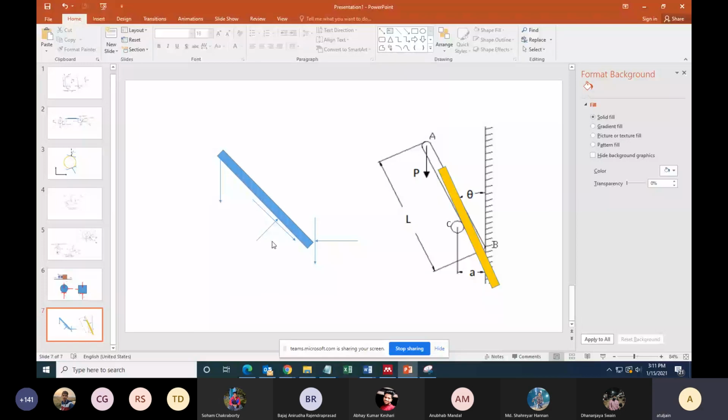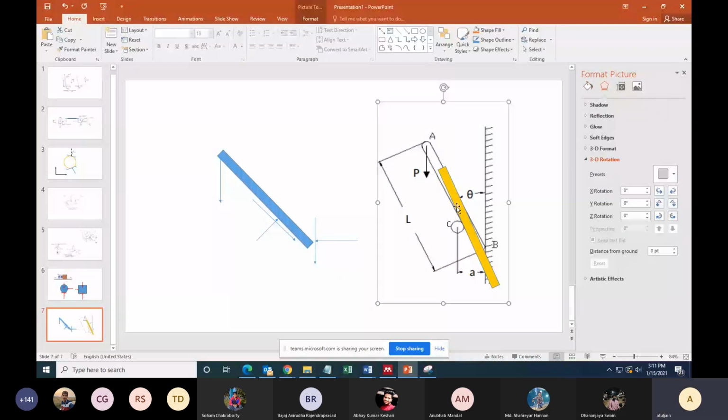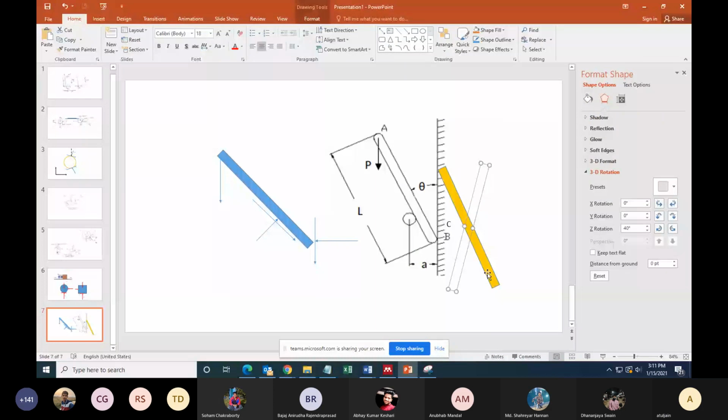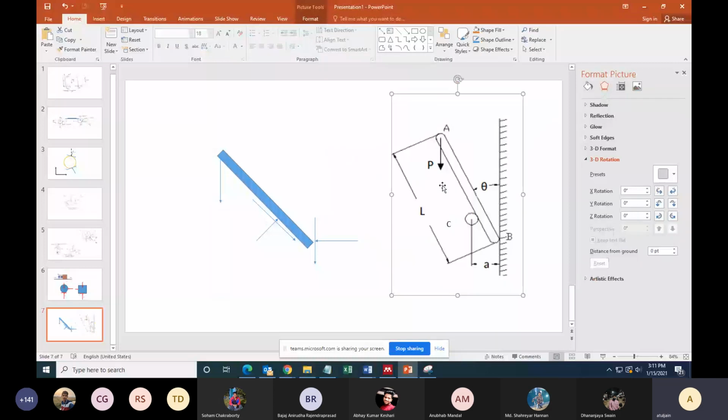Now, in the other case, what will change? In the other case, the direction of both the friction will be opposite. And what do we want to calculate? We want to calculate the ratio between A and L as shown in this figure. This A divided by L length we want to find out. For that, which equations of equilibrium do you propose? Sir, moment equation, moment about B, moment about C.